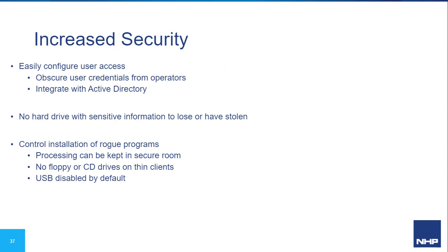Security, of course, is a big thing. I can easily configure the access for users based on credentials from Active Directory or stored inside ThinManager. Typically, I don't want the users to see system-level credentials. I might still want them to log on, and we can enable that. There's no hard drive on a thin client. If it is stolen, it becomes a brick, and there's no intellectual property, no algorithms, licenses, software, databases, etc.